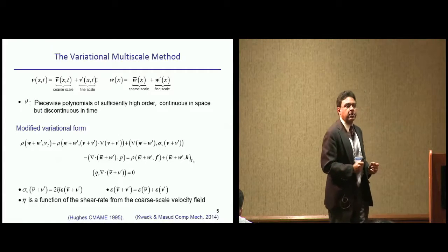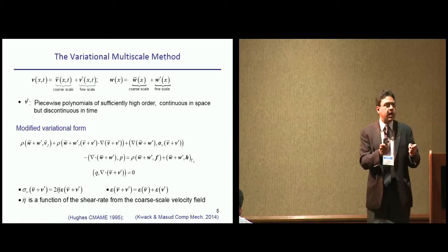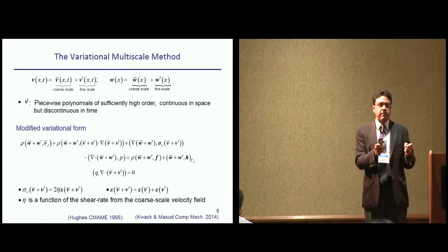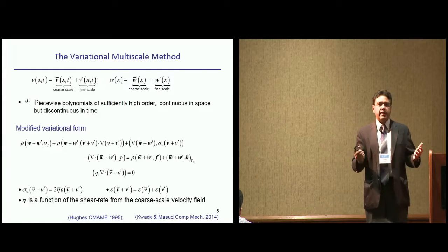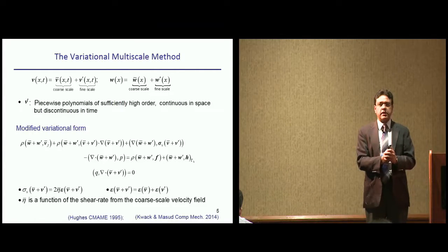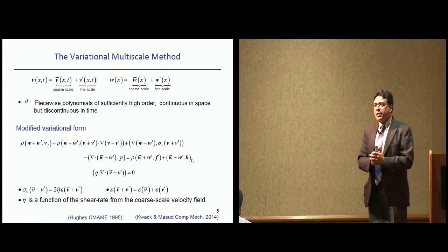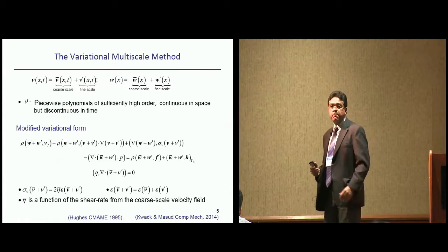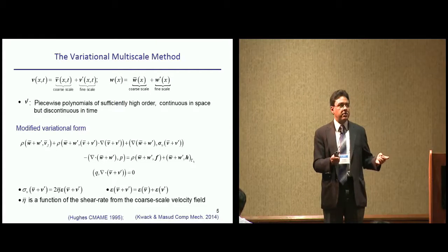It is able to capture physics which is larger than the characteristic length scale of the mesh, which is the size of the element. And all the physical features that are smaller than the size are dropped out. Okay, so we refine the mesh, we get better physics. But we can keep on doing that, and if we keep this line of argument, then very soon we can exhaust any computational platform.